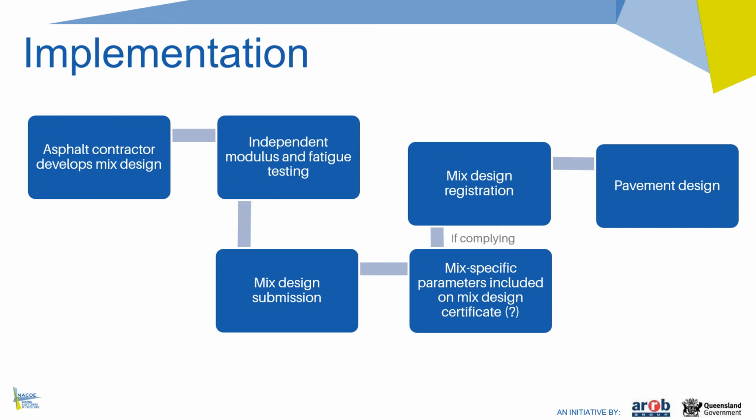The asphalt contractor would then engage an appropriate independent lab to do the independent modulus and fatigue testing using the procedures described by Eric and also detailed in the technical note. And that also includes fitting of the master curve and the fatigue relationship. The asphalt contractor will then submit those details to TMR, as is currently done with all asphalt mix registrations or mix design submissions.